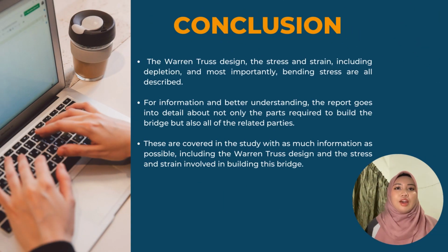In conclusion, FQA Construction Company's most recent project involved designing and constructing a pedestrian bridge. It was dubbed Old Street, has a length of 9 meters, a bridge deck span of 3 meters, and a height of 1 meter. It is situated at Lorong Jaafar, Kampung Bakri Muar, Johor. This bridge was built to connect and make it possible for pedestrians or villagers to travel from a residential neighborhood to an agricultural area. Ready-mix concrete of grade M25 is used for the beam and the column material is made of ready-mix concrete of grade M30.